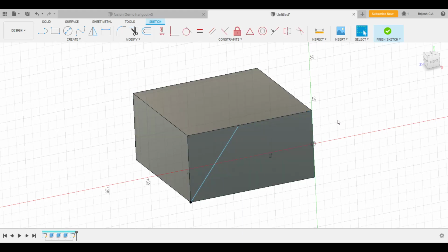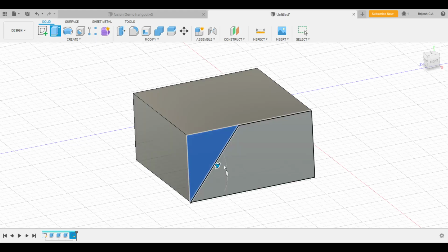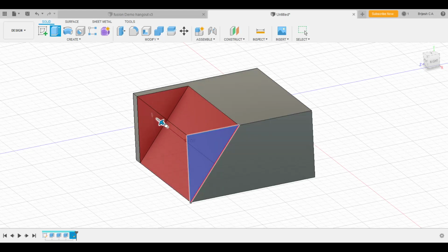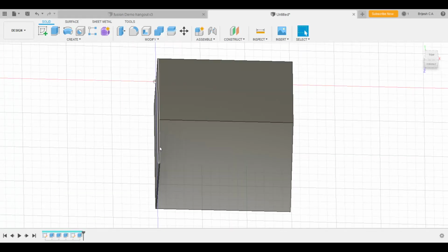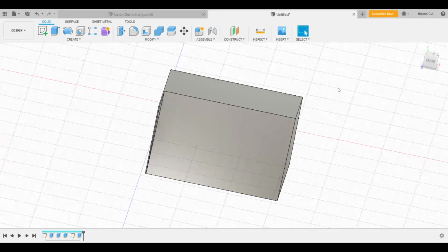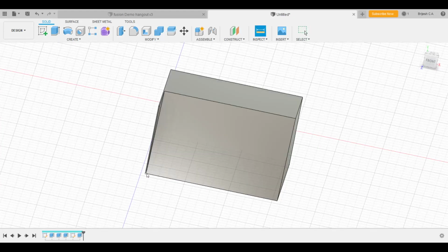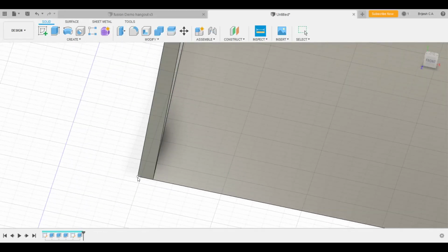So what I do is press on finish sketch, press on extrude, click on this surface and extrude it for whatever dimension that is, 75 mm, and press extrude. Now this is primarily because what you see in terms of distance, this is not 75. It is 75 point something.